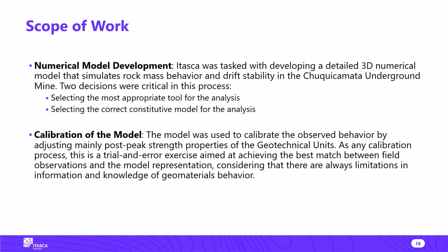An implicit addition to the process described here was that as soon as the constitutive model was selected and it became clear what variable was going to be interpreted to try and match the field observations, we developed routines to simplify the numerical output, in some way mimicking the simplification inherent to the use of the rock mass pillar to interpret the overall pillar behavior. We will describe this simplification later on in this presentation.